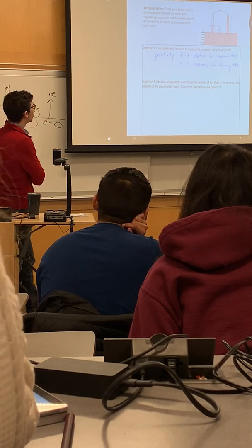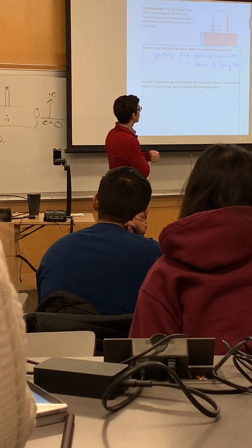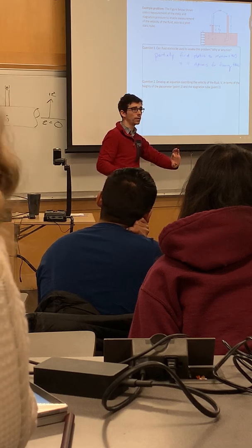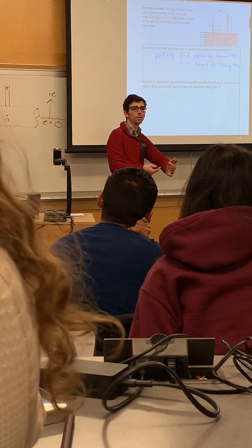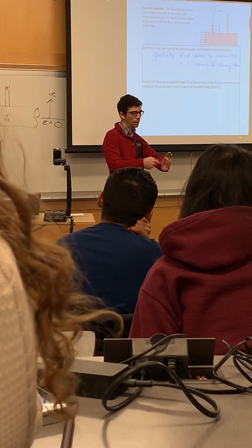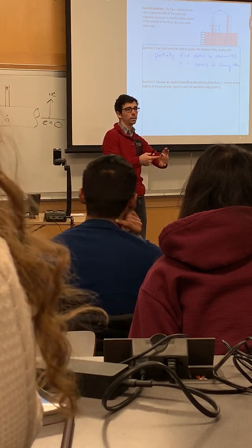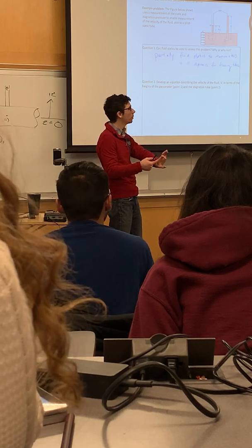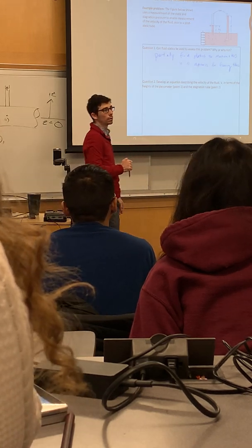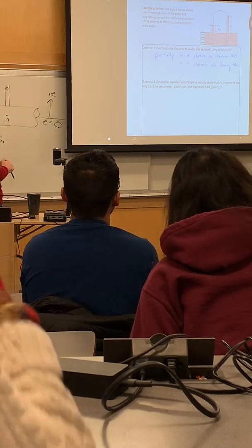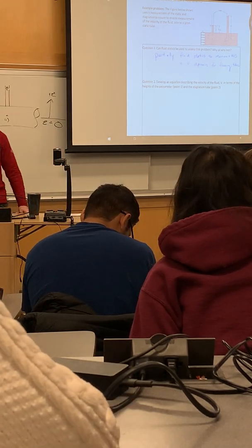So the pitot tube at point 2 is open to the flow. So it allows flow to enter, and then after it reaches a steady state, at the entrance to that open tube, we can assume that the fluid is static up through that tube. Okay, so that's why at point 2 we can take the velocity to be equal to 0.